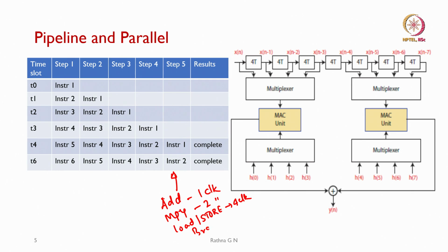branches in all these DSP processors, 6, 7, what I have considered, that is DSK 6713 and then 6748 LCDK board from the TI, they take branching of 5 clock cycles. So, these are the execution times that we need. So, these are basically the load and store architecture, what we call it. So, we know how many clock cycles each instruction is going to take.